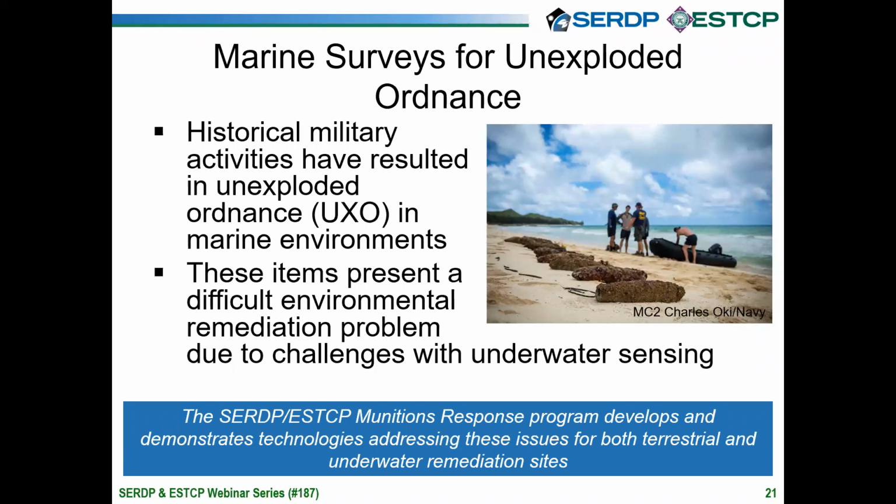This presents a pretty unique and difficult problem in the marine application because of the relative attenuation of electromagnetic energy underwater. So in marine applications, the sensors we generally turn to, because they have relatively weak attenuation, are acoustic sensors. These can have a fairly good standoff from the seabed. They can send out acoustic pulses that propagate into the bottom and scatter off targets, and then we can use signal processing to recover imagery.